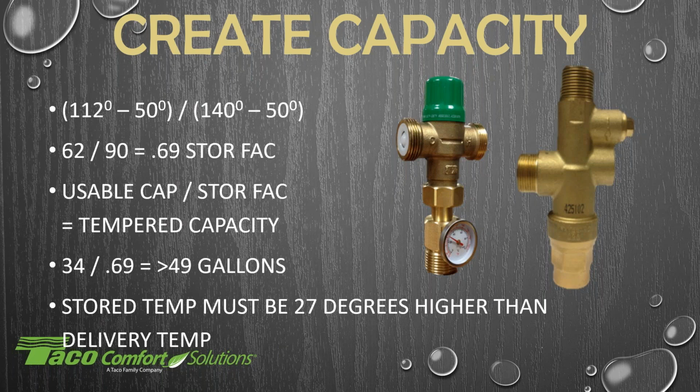There are also valves out there, and we have them also, that are a 10-degree spread. So just pay attention to the delta T of the mixing valve being used in the application, so that you have your stored temperature and your delivery temperature either 10 or at least 27 or more. You can do it further. You can easily do it further. You can change that temperature from that 140 to something higher. And that's what I did in my home.